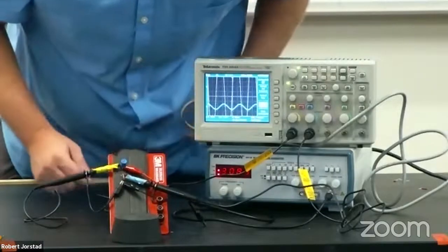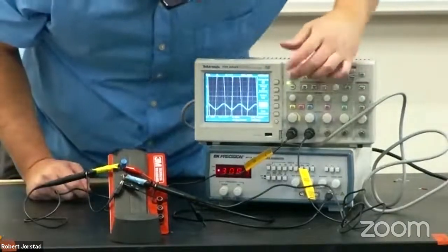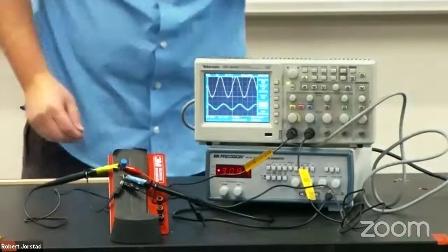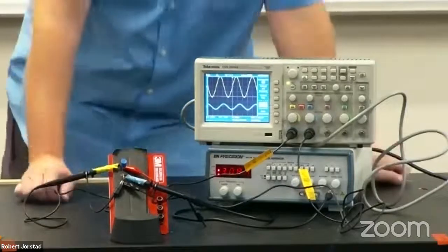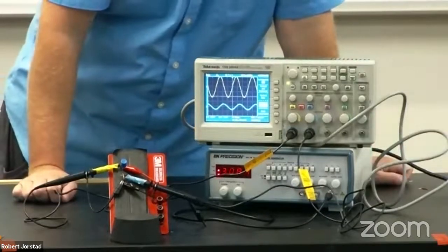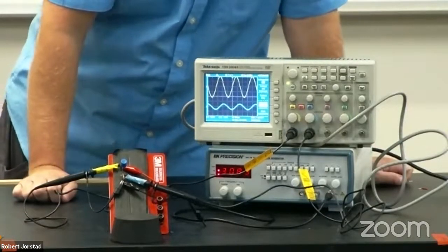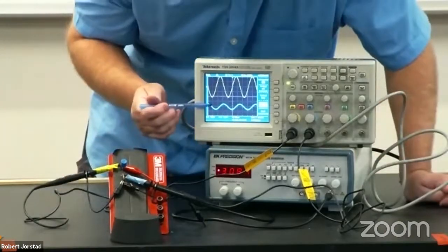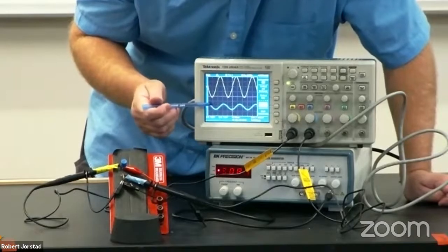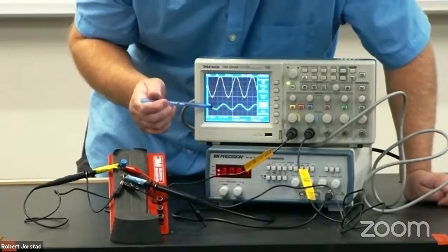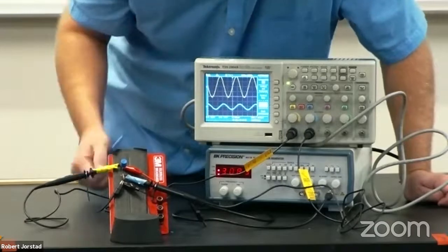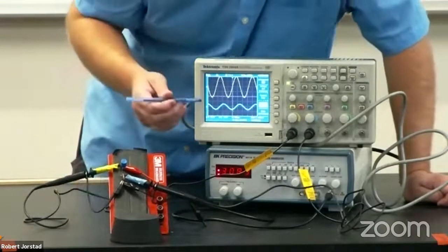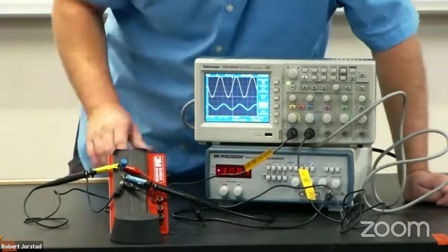Right? And so in this case, let me get these both on screen here. Now we're seeing the curves are not exactly the same size. They might not even line up that perfectly if we look carefully. Just a minute on that. But I do want to point out, remember, the voltage across the resistor, if you divide that by R, it's the current. So I want you thinking of the yellow curve or the upper curve as the source voltage as a function of time. The lower curve is the current as a function of time.